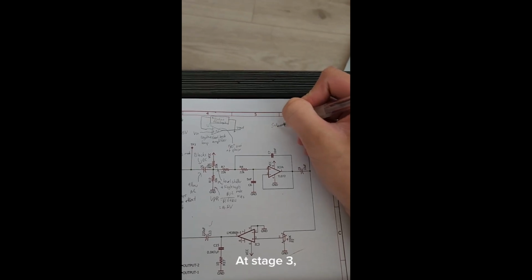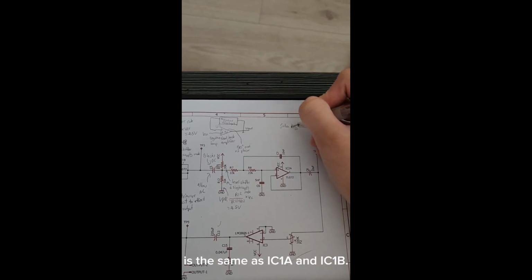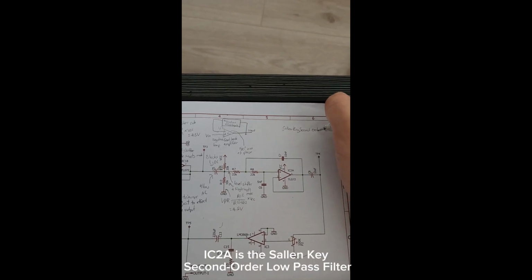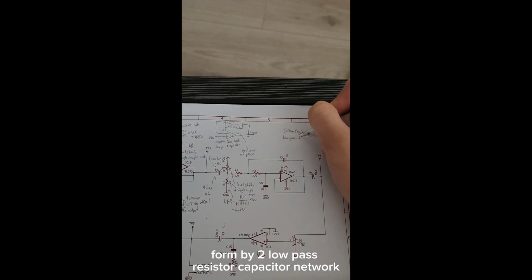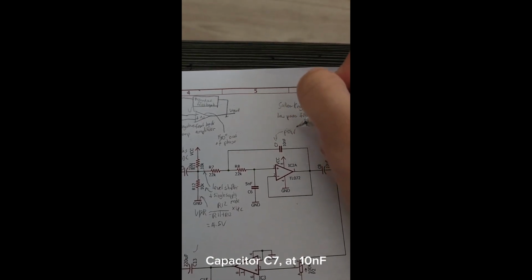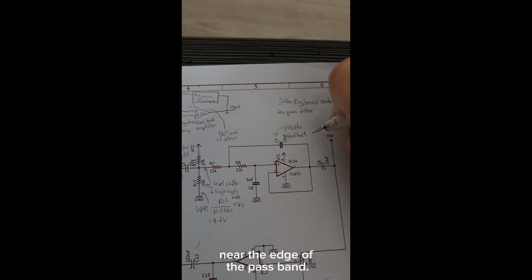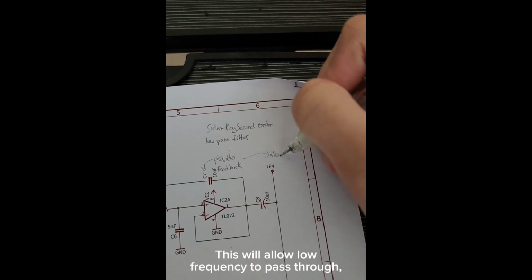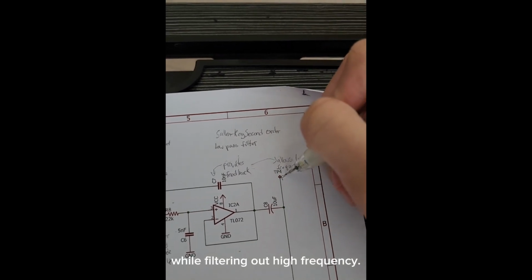At stage 3, IC2A, which is TL072, is the same as IC1A and IC1B. IC2A is a Sallen-Key second order low pass filter formed by two low pass resistor capacitor networks. Capacitor C7 at 10 nanofarads will provide the feedback for shaping the response near the edge of the pass band. This will allow low frequency to pass through while filtering out high frequency.